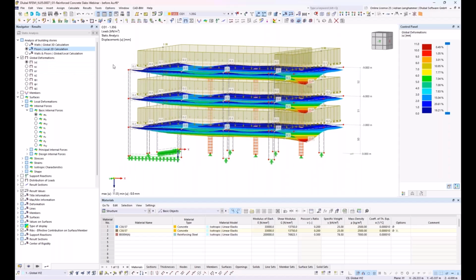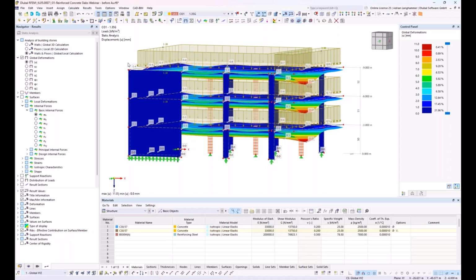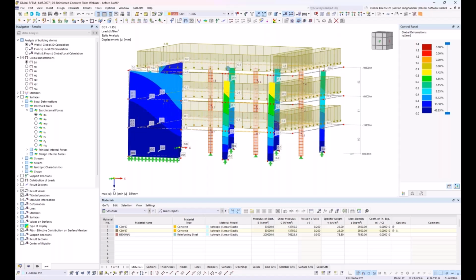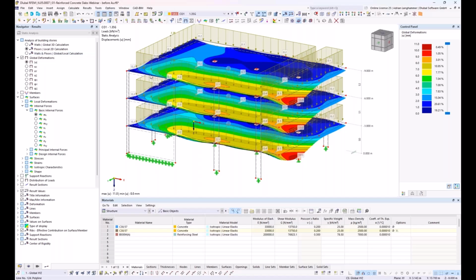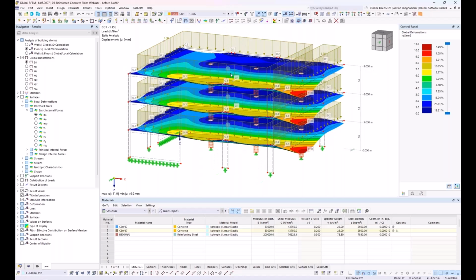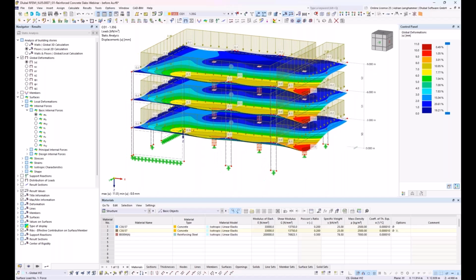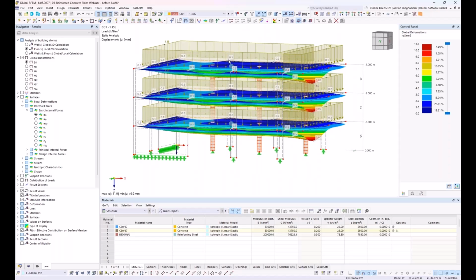Yeah, I also will show another point. The program, as I mentioned, calculates the walls here, connected via rigid diaphragm, and the floors, let's say, as separated 2D positions, and it also calculates some load transfer based on a submodel which is calculated in the background.